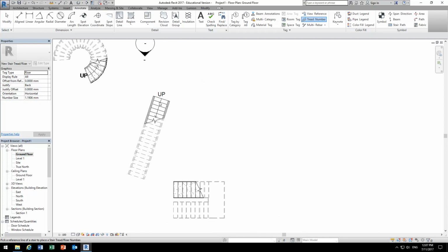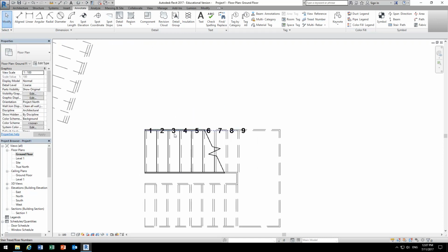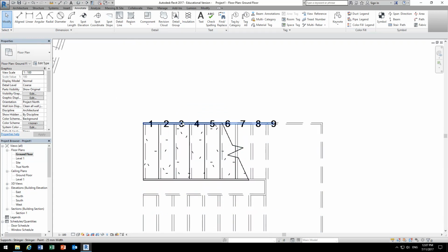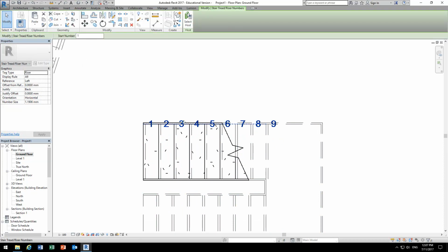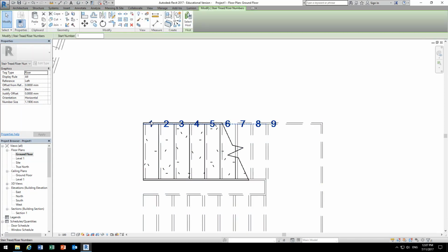So that's not going to work on this one because that's stair by sketch. And it gives you a location where you get inside, middle. It's actually better, and you can then define all of that in the family. So it's great. It works better than stair by sketch, and you can move it. I think from memory, or do you have to edit the family? At North Point, in terms of section, the automatic stair numbering was obscured. It was just that they could move it up or move it down just to get it a little bit. Oh, you can, yeah.